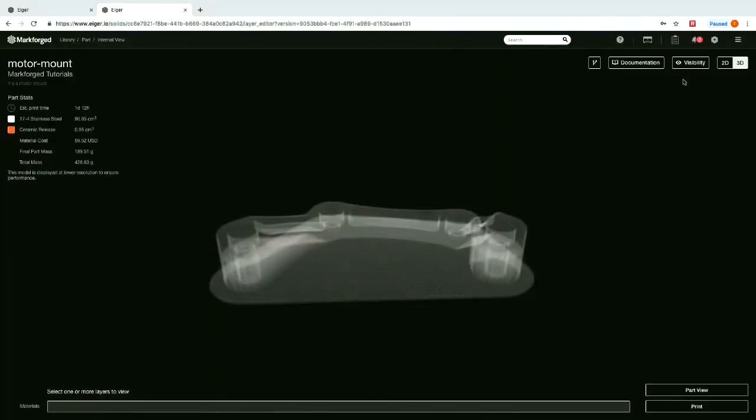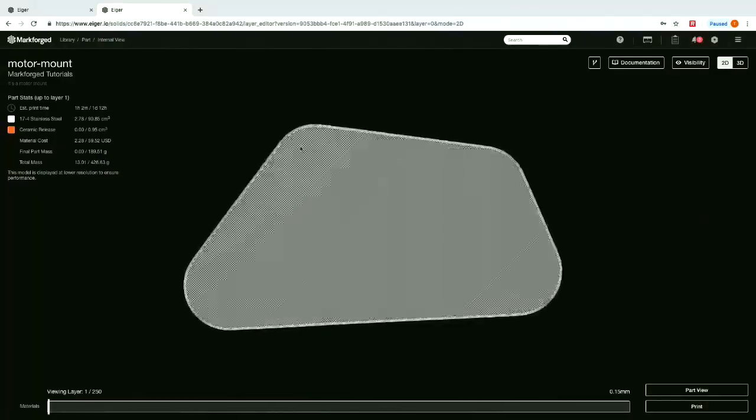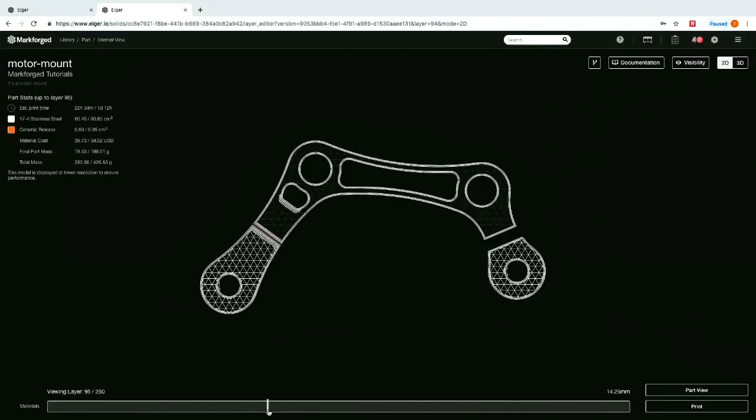So any of our parts, they're just metal parts when they're done. So you can polish them, or you can post machine them, you can do any of that stuff. The one thing that we'll note is that because our parts have open cell infill, the walls are relatively thin on the part. One thing we're doing now is working to get variable wall thickness and making that a changeable feature. But the thickness of the wall here is basically your machinable area. So you can definitely polish it. You wouldn't be able to remove a significant amount of material without blowing through the wall there.